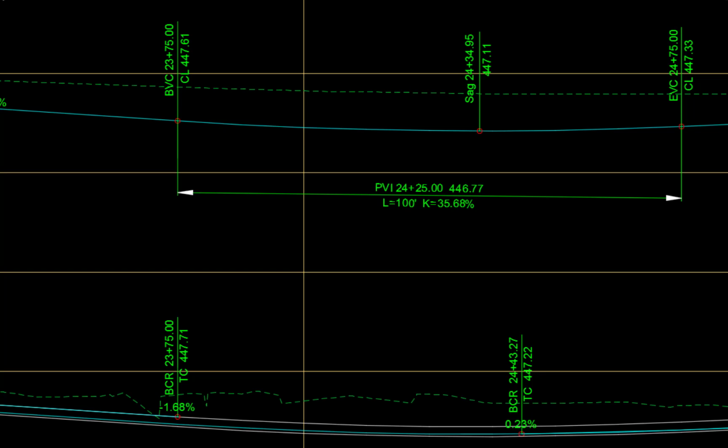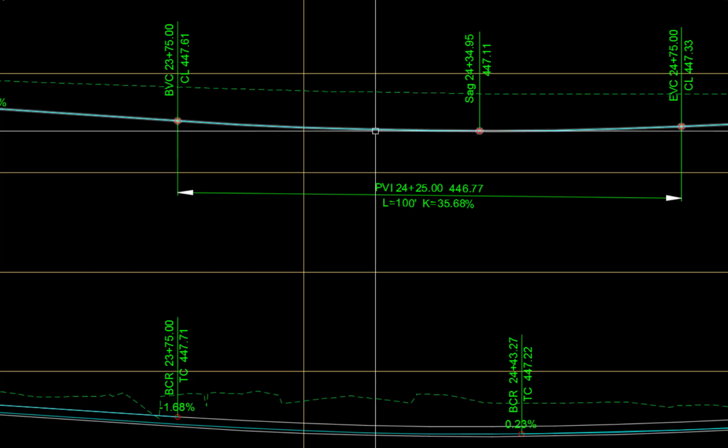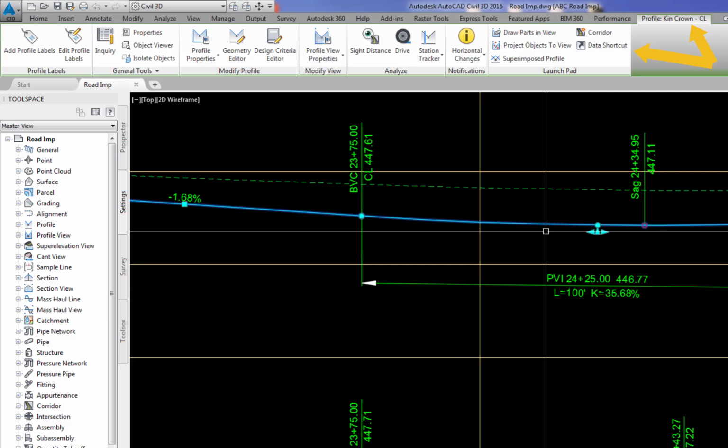When a Civil 3D object is picked, the context-sensitive ribbon tab associated with that object will automatically be displayed. The Add Label icon is generally located in the far left portion of the ribbon. Some context-sensitive ribbon Add Labels icons contain a top and bottom part, while others contain only a single part. The parts are displayed when the cursor is moved over the icon.